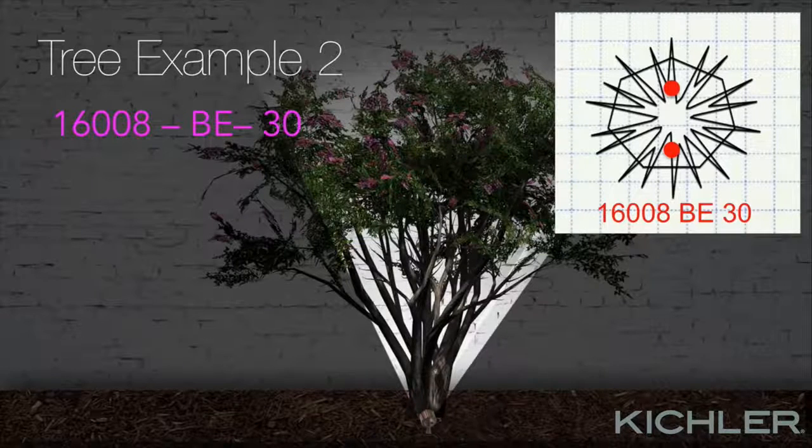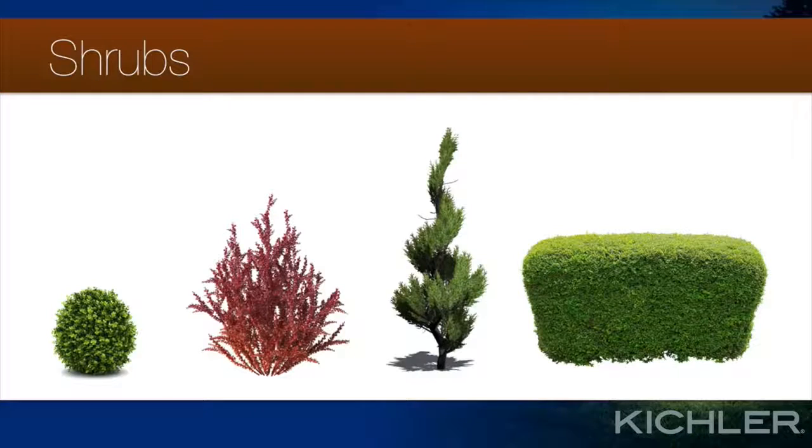Specifying fixtures and drawing them on the plan works in basically the same way for other applications, so we'll discuss other situations more generally. Shrubs come in a variety of different shapes, from round to V-shaped to topiary and hedges. There are a couple of common lighting goals with shrubs, including full illumination of a shrub to create a point of interest in the landscape, to grazing of hedges used to establish rhythms. Here are some effects and the fixtures that would create them.